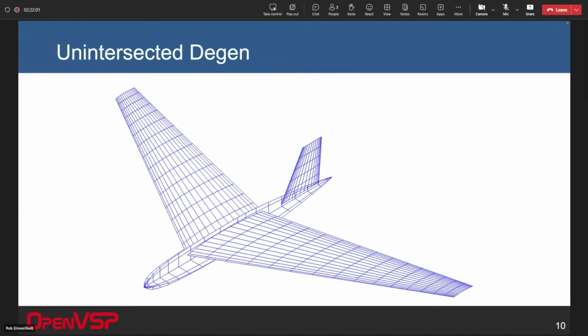So when we would do degen, we would smash all these down to thin surfaces. And you see that the wing becomes this curved mean camber surface, and the fuselage becomes this cruciform, and the tail is a flat plate that then is coincident and overlaps with that vertical part of the cruciform on the body. And so in a degen geom, which is what VSPAERO was originally written to work with, no intersection calculations are performed between these. There's no trimming, there's no union. These are all just separate panels that happen to be flying in close formation with one another, with no actual connection between them.